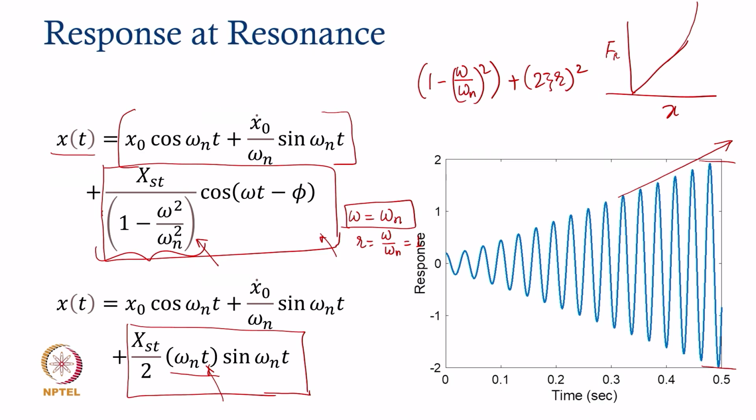The other thing is, most of our vibratory systems are contained. If you consider gas turbine or steam turbine rotors, which are vibratory systems we discussed, they are always limited by the surrounding structures. Like in gas turbines, you will have a cylindrical stator around it, or seals surrounding the shafts. So there are containing structures which will again limit the growth of these vibrations.